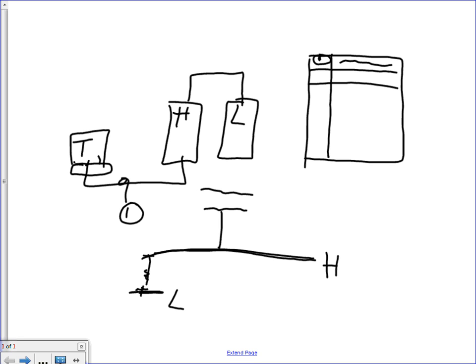Again, I'm not the best drawer, but that's the basic explanation of the differences between the two. For a one line, you would list this breaker in text right next to it, whereas here you would have a schedule that lists all the breakers in panel H separately, besides having feeders in a separate schedule. Does that make sense? I'm trying to make it as crude and basic as possible. The main thing is understanding that there are two ways of showing the same information.